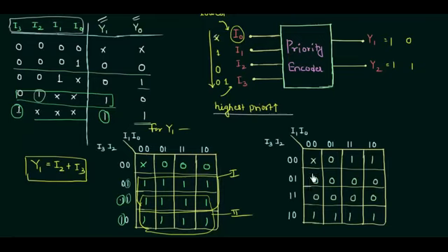One more important thing that you can see in this K-map is for I2. If I see for I2 when it is 1, which means this row and this row we have to see, we have put 0, but when I see I3, which means again this row and this row, it's 1, so there is a contradiction in this row, it's 1 and 0 both, so I will take it as a don't care for us, and we already know how to operate with the don't cares. If it is a don't care, I can take it as 1. So let's start making the group.